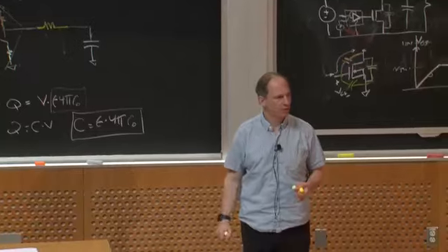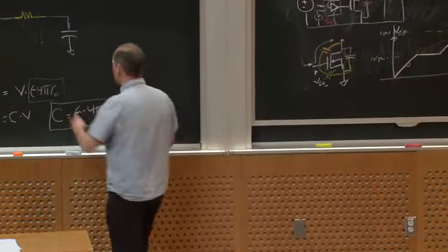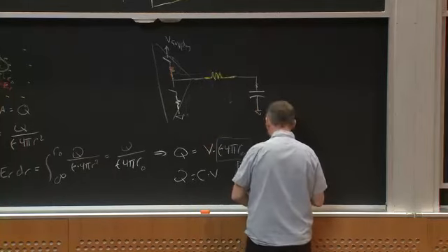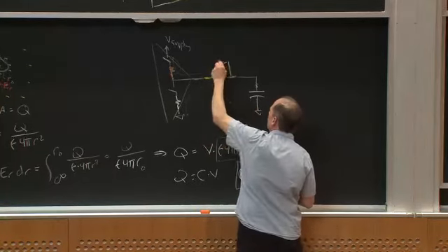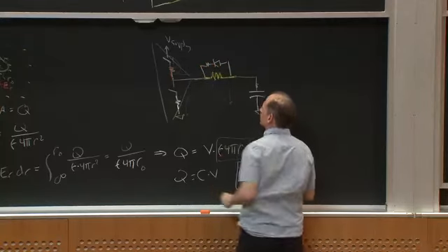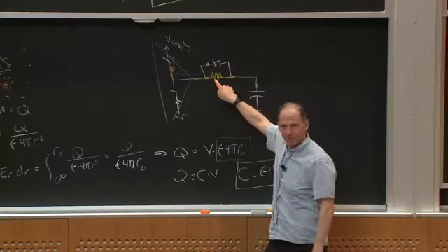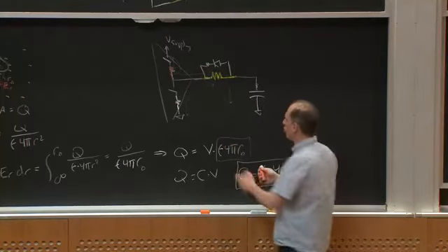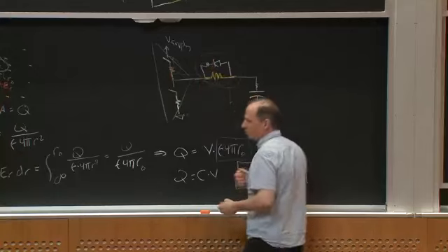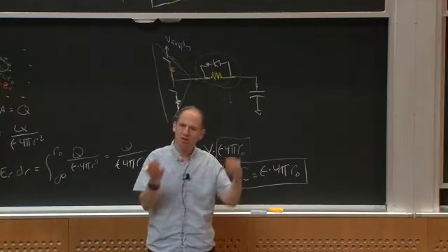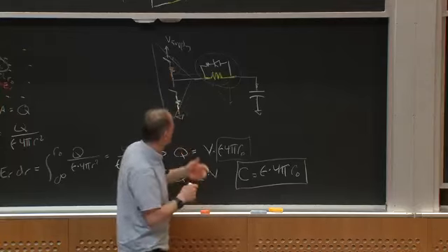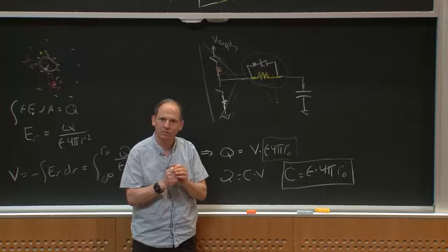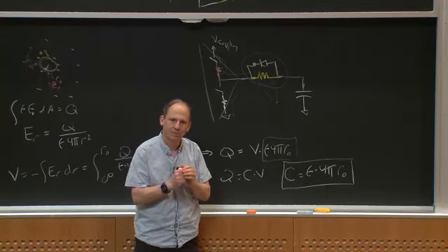If you don't like what that looks like, you can add your own resistor that'll slow down the turn on. Maybe you don't want to slow down the turn off as much, so for the turn off, maybe you put a diode and a smaller resistor, or no resistor here. So he charges slowly through the yellow resistor, and he discharges quickly through the green diode. Okay? So you can control the rate of turn on and turn off to control that switching and the noise injection elsewhere in your circuit. And you think about that when you buy your driver and how you connect your driver to your switch. Questions about that?